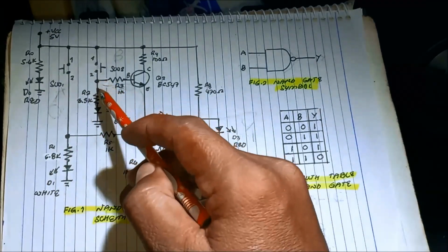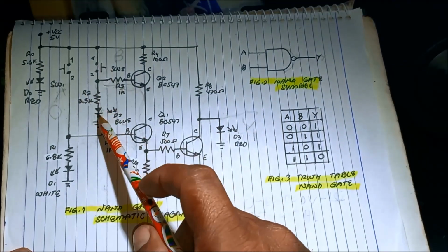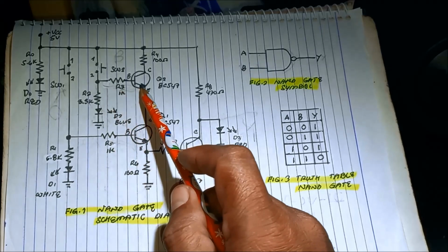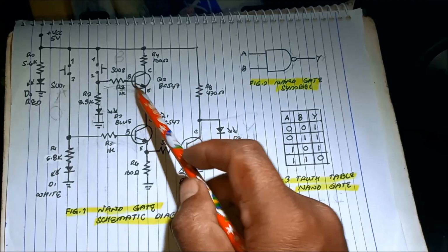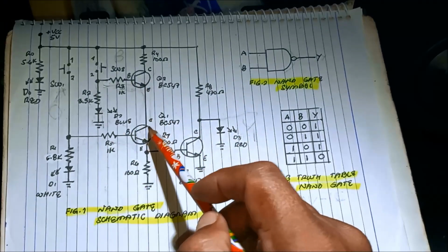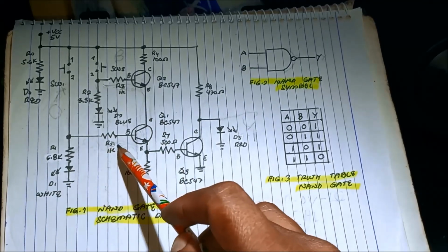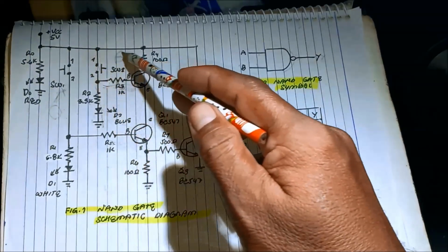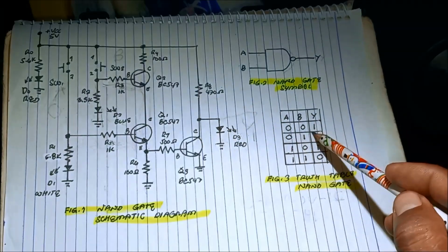So current will only flow into the input LED, turning it blue, and it will not pass to this transistor. The transistor is still open because there is no base current, so no current flows from collector to emitter to the ground. That's why current is still going to the output, still 1.